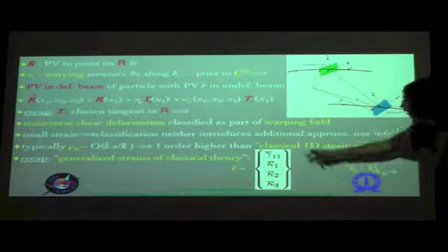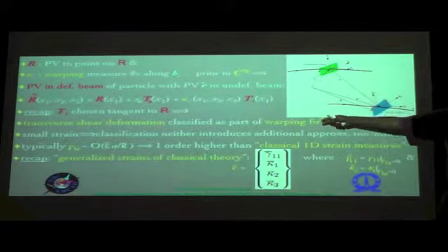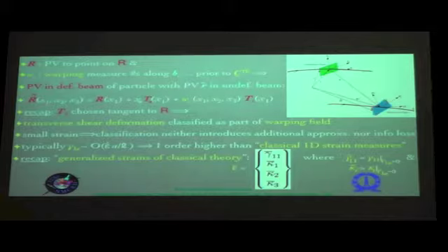So these 4 are called the classical 1D strain measures, and they are in turn related to the 1D strain measures that we defined in the previous class, which are basically the ones without the bars. They are taken under the special case that gamma 1 alpha is set to 0 here, so that it is in turn going into the warping and therefore appears in this term to get the same position vector R hat, big R hat as before.